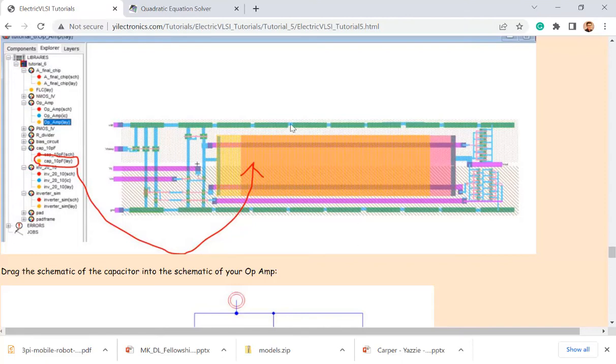So that's the top rail, which is VDD. And here's the bottom rail, which is the ground. And you keep all your transistors, the PMOS on the top usually, NMOS at the bottom. PMOS, NMOS, PMOS, NMOS, right? So when you do the layout, you need to make sure that they have the same height. So you can keep them in the same 2 rails, top rail and bottom rail, just keep them inside. Then you find out the height here and calculate the length. You know what I mean? You don't want to make the cap too big. It has to be within the 2 rails.